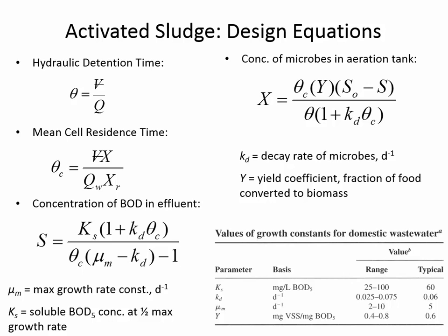Here are the design equations we're going to use in an example I'm putting on the board in just a moment. We go through them step by step. We start, when we do our design, of considering the detention time of the liquid, then the detention time of the cells. We calculate what detention time corresponds to a certain outflow concentration we need, and so on.